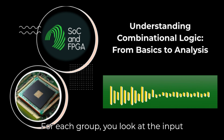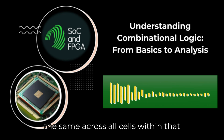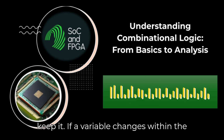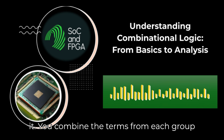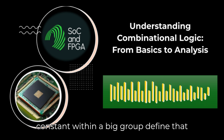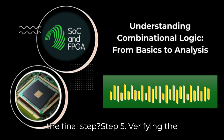Once you have the groups, how do you get the simplified expression? For each group, you look at the input variables. If a variable's value stays the same across all cells within that group, always 0 or always 1, you keep it. If a variable changes within the group, is both 0 and 1, you eliminate it. You combine the terms from each group with ORs. Right. Variables that are constant within a big group define that simplified term. Okay, makes sense. What's the final step?